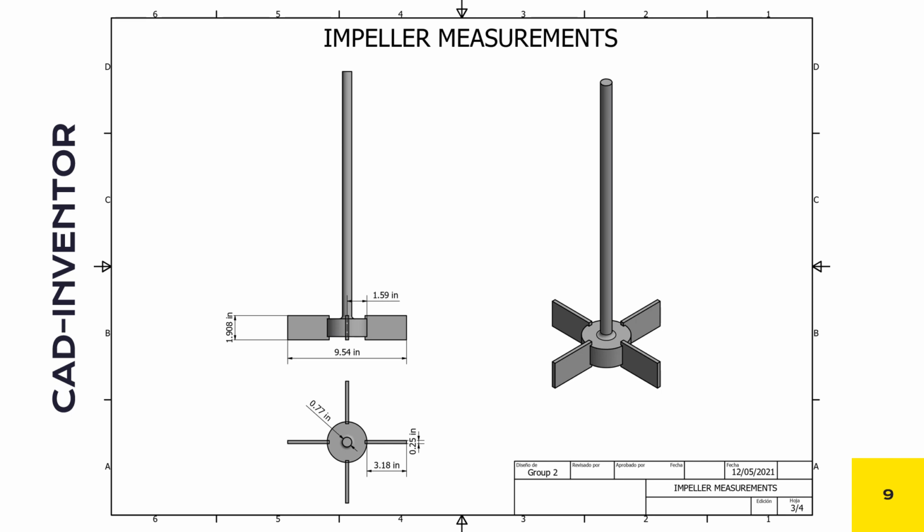For the creation of the impeller, different bibliographic sources were taken into account, most of which suggested that the blade measure must be between 50% and 80% of the diameter. For this case, 75% was taken.